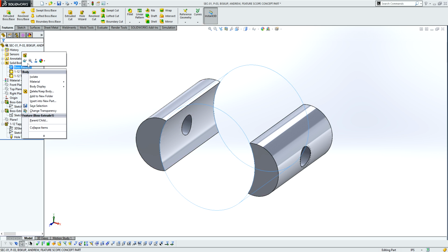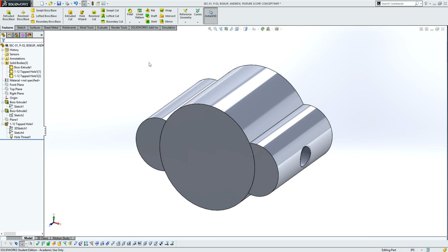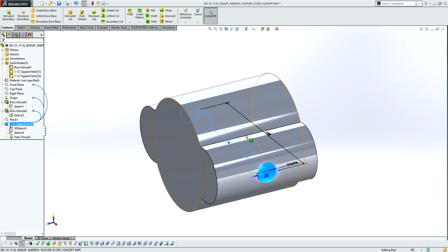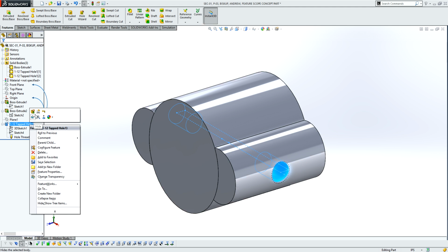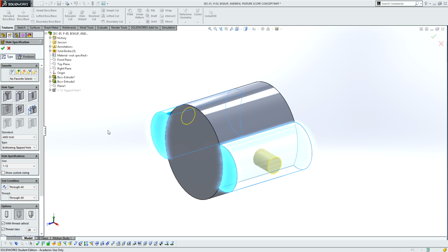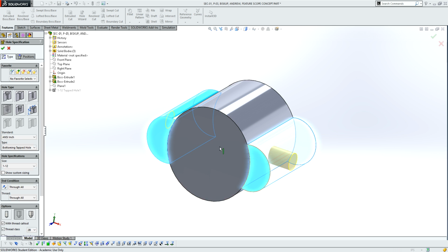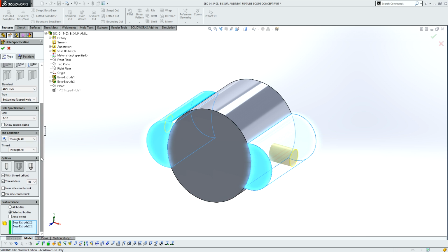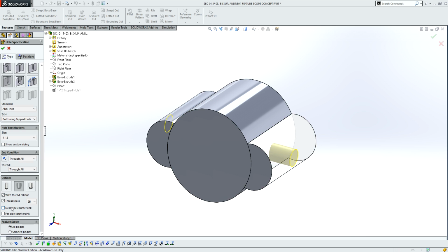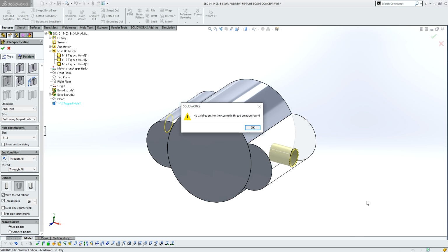So I'm going to unhide this again, or show, unhide, same thing. So this tapped hole. This hole, most of the time if you did a through hole, it would go all the way through. Well, we have multiple bodies here, so we can actually have a few different options. If you scroll all the way down, you'll see this feature scope. Most of the time it's all bodies, so then when I select check, I'll go ahead and stop right here.